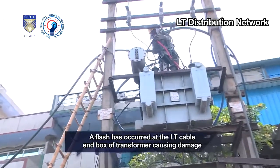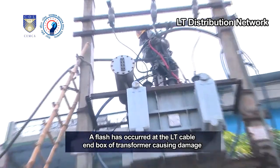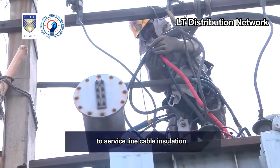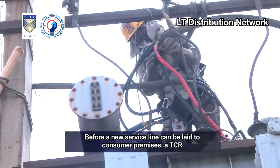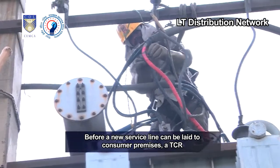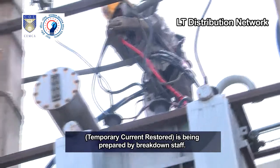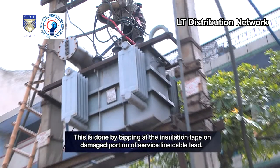You can see that a lineman is repairing the LT service cable emanating from transformer to consumer premises. A flash has occurred at the LT cable end box of transformer, causing damage to service line cable insulation. Before a new service line can be laid to consumer premises, a TCR, temporary current restored, is being prepared by breakdown staff. This is done by taping the insulation tape on damaged portion of service line cable lead.